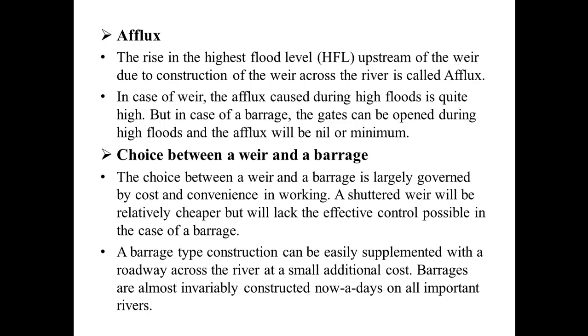Whereas in barrages, when a flood comes in the river, the gates are opened and the flood water is allowed to move to the downstream side, so the efflux is minimum, as the highest flood level is at the lowest level.